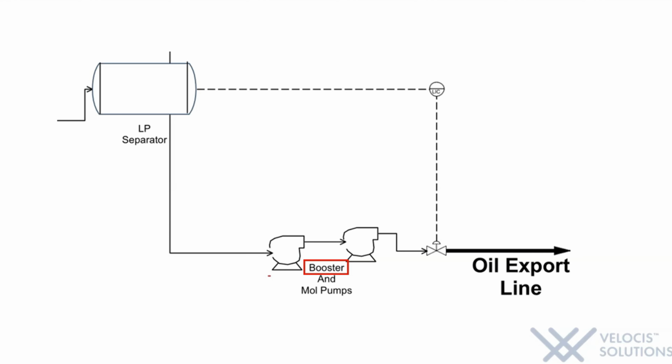The first pump, the booster pump, which is slightly smaller, serves for increasing the pressure of the liquid to the determined mid-pressure value of 2800 kilopascals right before the entrance of the main pump. This pressure increase is especially determined through several steps of calculation and aimed to prevent the formation of cavitation, meaning high-pressure collapse of bubbles formed due to the boiling of the mixture at low pressures in the pump.